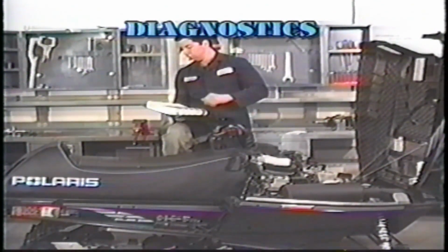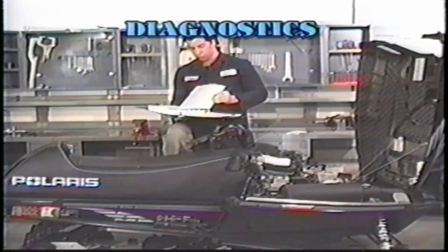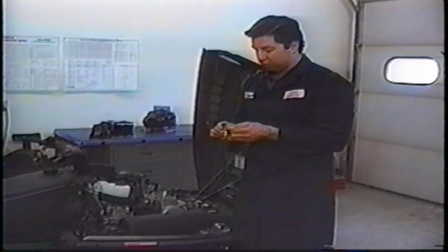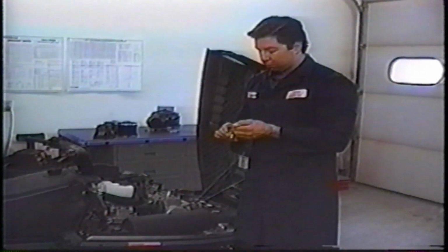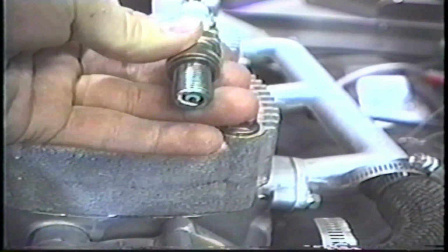Sometimes, diagnosing spark-related problems may seem overwhelming. However, following a step-by-step diagnostic process will quickly lead you to the cause of the problem. First, verify the problem. Check to see if the ignition system is producing good spark. Always verify spark with a new, properly gapped spark plug. The plug may look good and still be partially fouled.